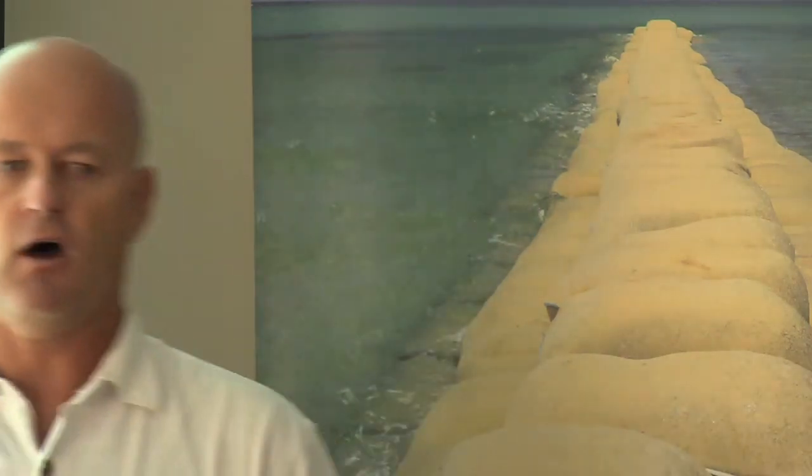With rock structures, the generally accepted coastal engineering standard is you're allowed to have up to 5% of rocks move from where they started, and that's still considered no damage. Because there's a lot of flexibility in rock structures, 5% of the rocks can move from where they started, and it's still considered a no damage criteria, in inverted commas. For geotextile containers, there's still flexibility compared with a rigid, solid structure, say a brick wall. There's flexibility, but probably not as much as a rock rubble structure.